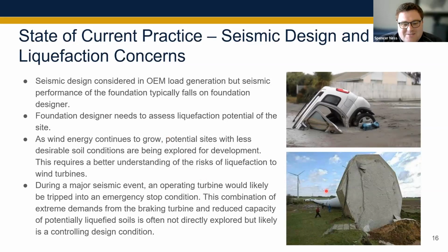Just to call out here, this image is not necessarily, or I don't believe is, of a turbine during a seismic event. I believe it's just an undersized foundation. But you can imagine, right, if we lost support of the ground from a liquefaction event, we could certainly see some sort of toppling like this as we lose support, particularly for these gravity foundations.